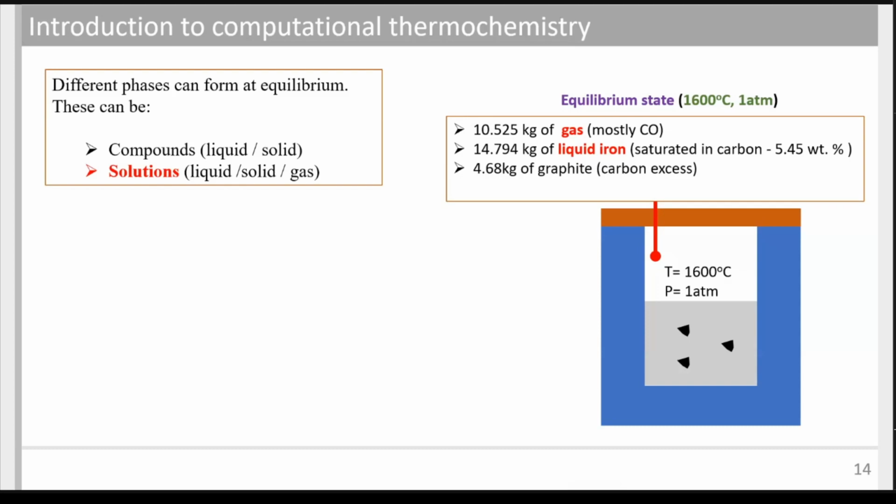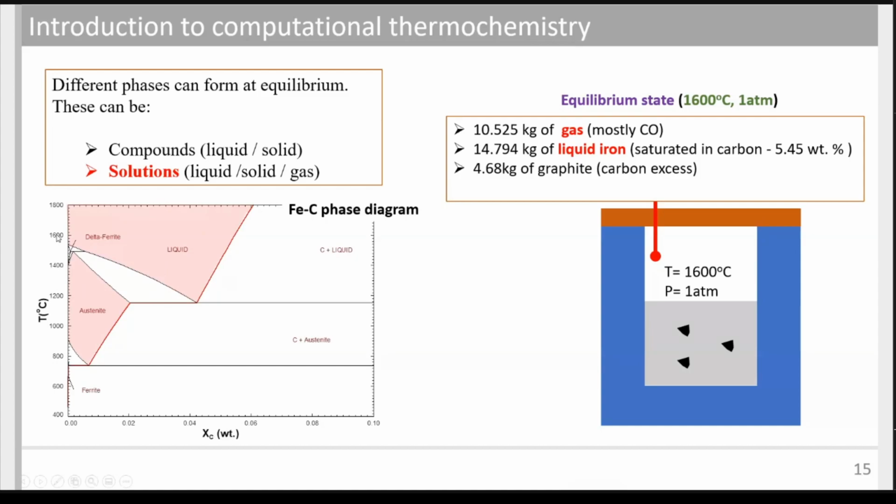If we look specifically at a phase diagram, and I think this is important because in the documentation you will see that I often refer to the documentation to see if a system has been optimized or not. I'm taking here the iron-carbon phase diagram at equilibrium. The line here is the solvus of graphite, not cementite, so this is the true equilibrium phase diagram. And what I did here is that I highlighted in red the zone where we have a monophasic solution, a region of one solution.